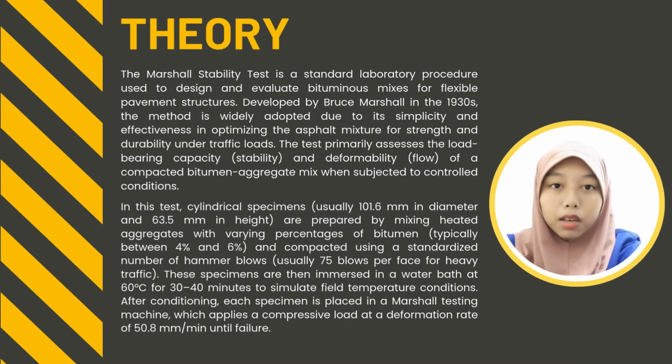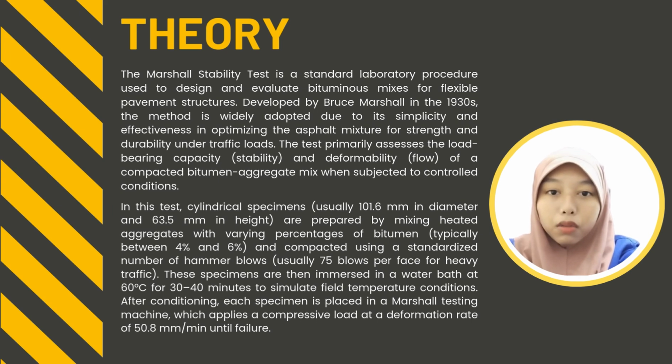I will explain the theory behind the Marshall stability test. The Marshall stability test is a standard lab procedure used to design and evaluate bituminous mixes for flexible pavement. It was developed by Bruce Marshall in the 1930s. This method is popular because it's simple and effective in improving the strength and durability of asphalt mixtures under traffic loads. The test mainly checks two things.